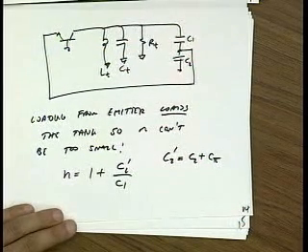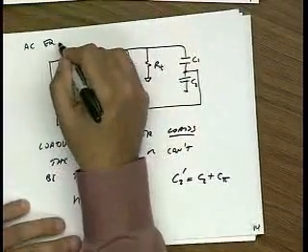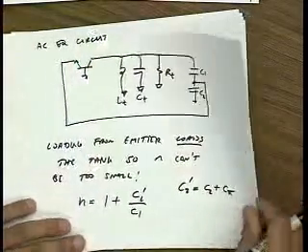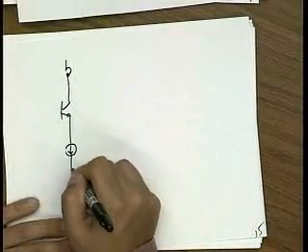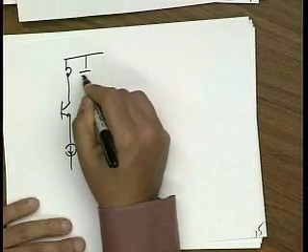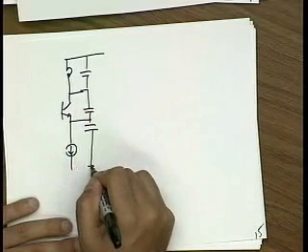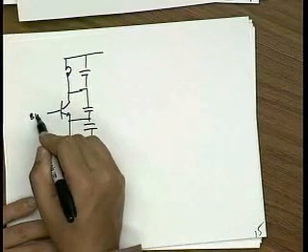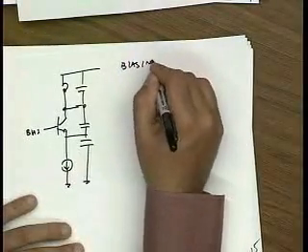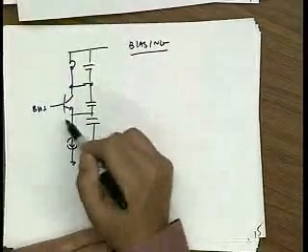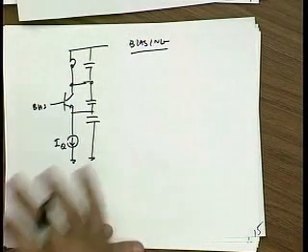Okay. So this is the AC equivalent circuit. The way we actually bias it looks a little bit different. I'm going to bias it with a current source here. Again, I can have this capacitor here, and then I'm going to have a capacitor to ground here, and this would go to a bias voltage. And you can see now that the bias current of this device is fixed by IQ. So the analysis that we did applies exactly the same.